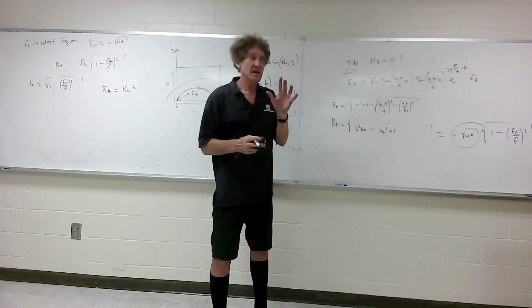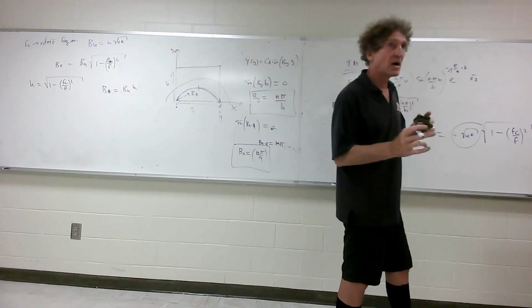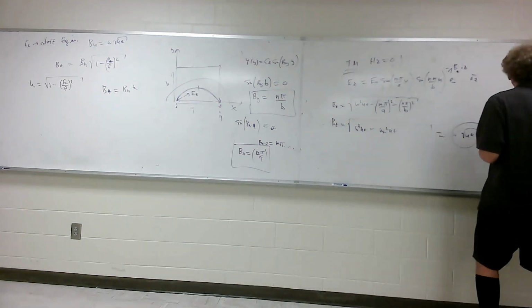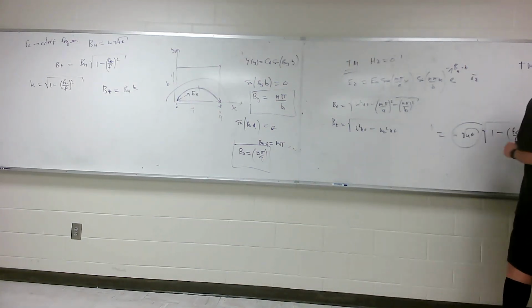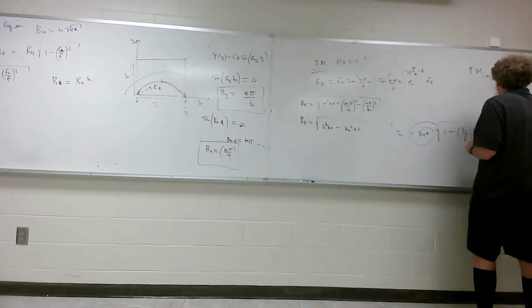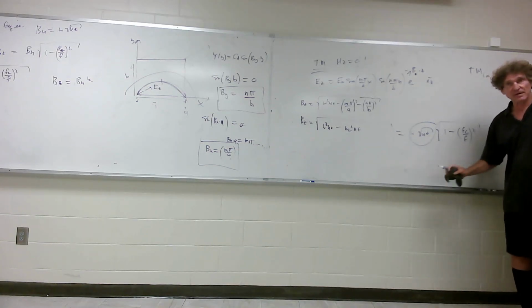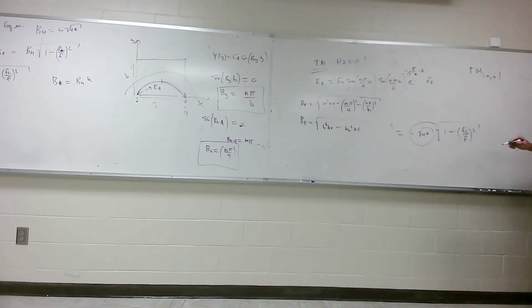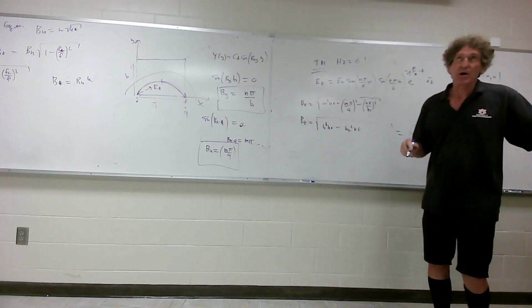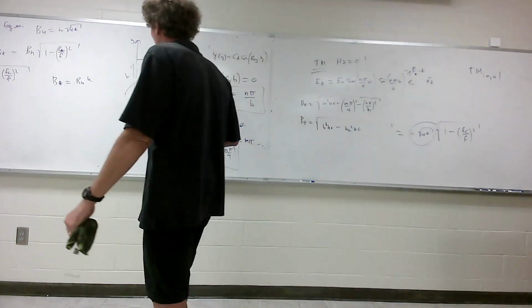Anytime you talk about a TM wave and the mode it's operating in, usually they'll use the symbol TM with M, N. TM says the waveguide's in the TM mode. That's the operational mode, how the fields are being developed and rendered. But the lowest order mode, meaning the smallest frequency of operation that it could work at, requires that both M and N are 1 in order for propagation.